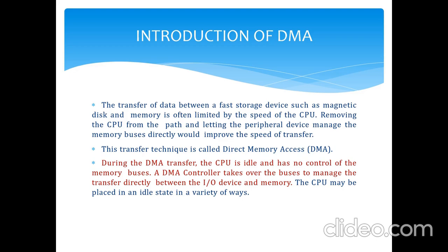Computers that have DMA channels can transfer data to and from devices with much less CPU overhead than computers without a DMA channel. Similarly, a processing circuit inside a multi-core processor can transfer data to and from its local memory without occupying its processing time, allowing computation and data transfer to proceed in parallel. DMA can also be used for memory to memory copying or moving of data within the memory.